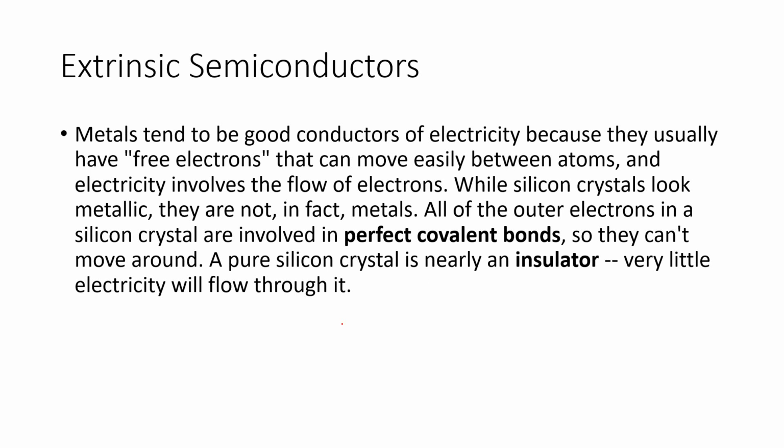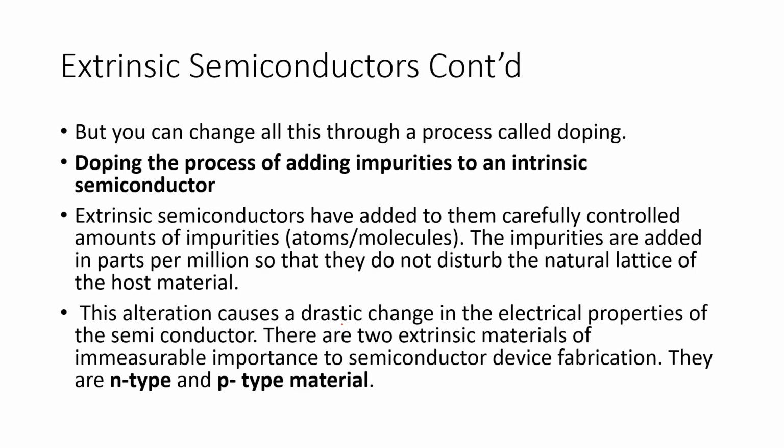So we know that already, that with pure silicon, right? Because of how it is structured, all of those perfect covalent bonds and all of that, it does not allow electricity to flow. What we're getting into now is to understand how an extrinsic semiconductor works, right? So based on what we just said a while ago, if you have pure silicon, the possibility of allowing electricity to flow is going to be limited because of the fact that the covalent bonds are there.